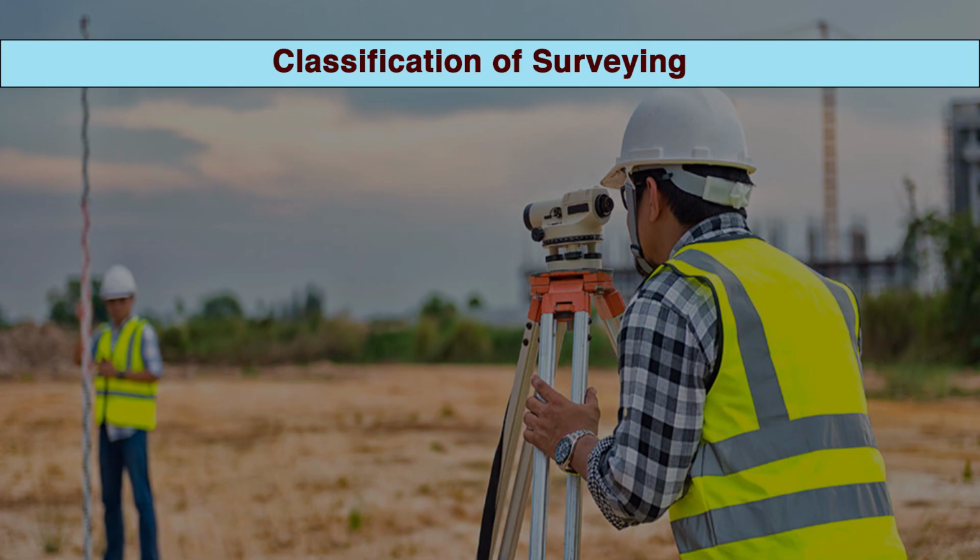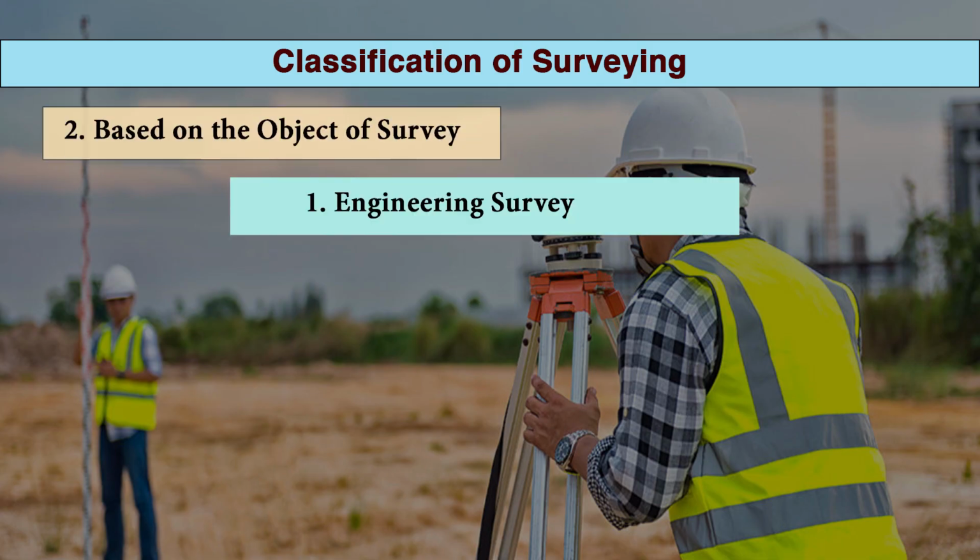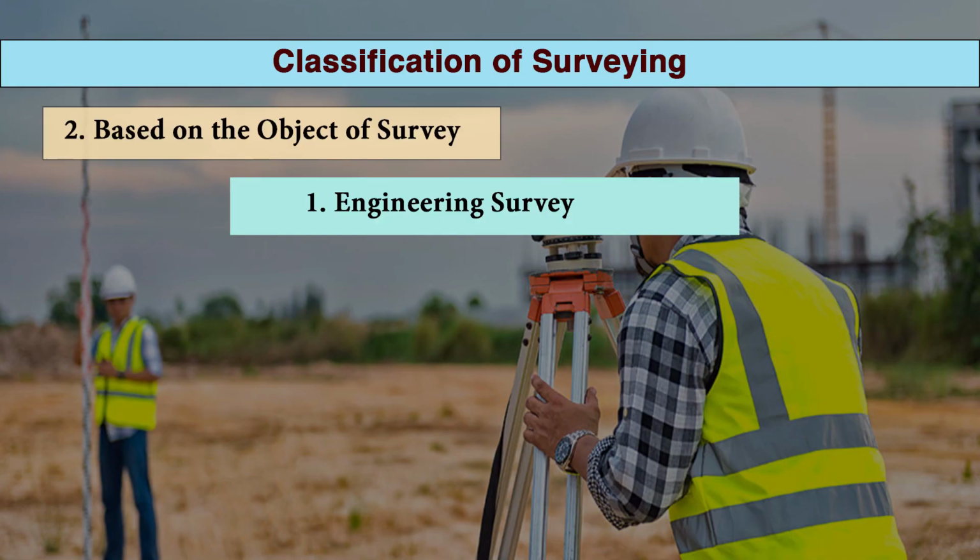The second head of classification is classification based on object of survey. First one is engineering survey. Engineering survey is conducted to obtain the data required for design and construction of engineering works such as roads, reservoirs, canals, sewage disposal and water supply systems. We generally observe people using a dumpy level for surveying in areas where road construction is ongoing. This is an example of engineering survey.